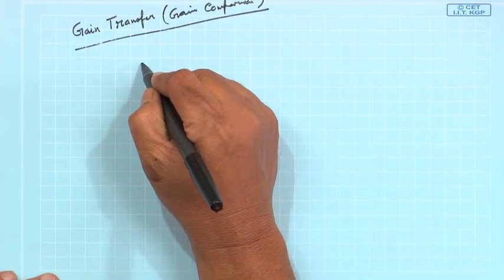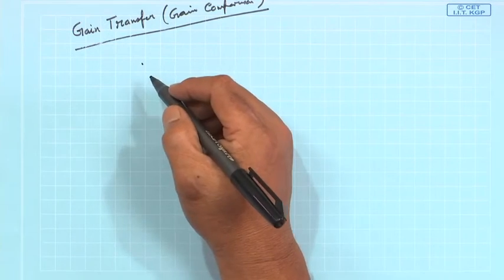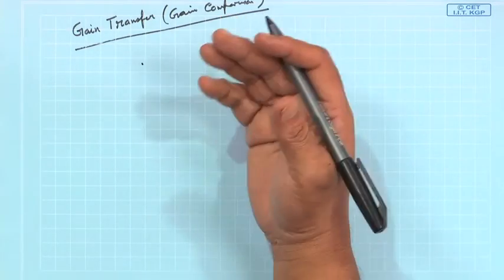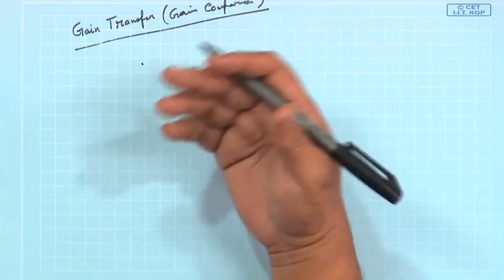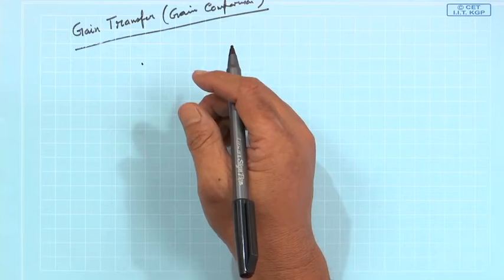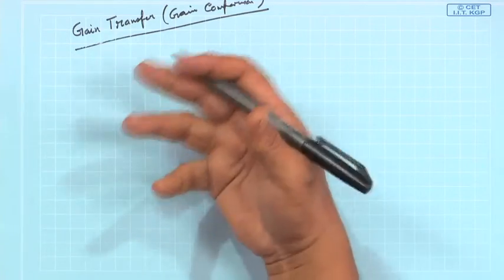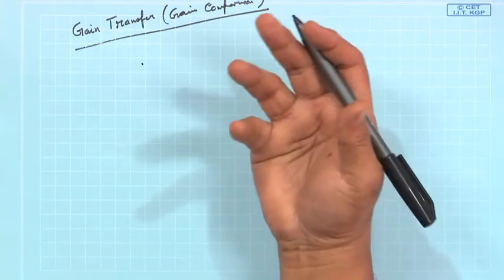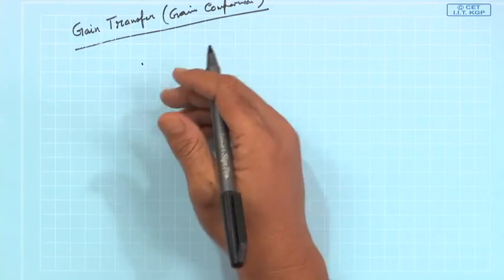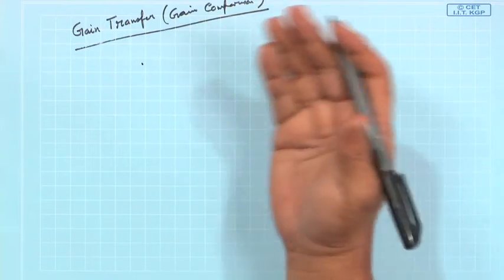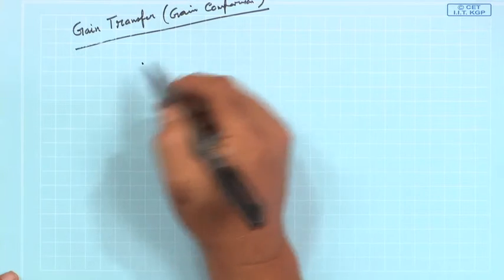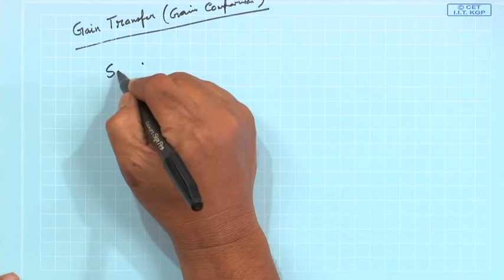There are standard antennas, and they are generally made of 2 types. One is a half wavelength dipole, whose gain is 2.1 dB, or a horn antenna. Any required gain can be found by measuring the dimensions of the horn. So, these are mainly the standard antennas, and you need a standard antenna for these measurements.